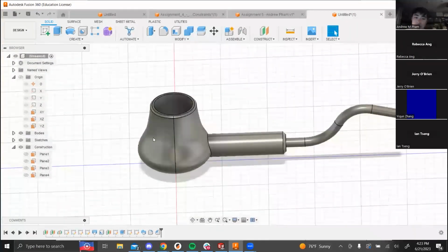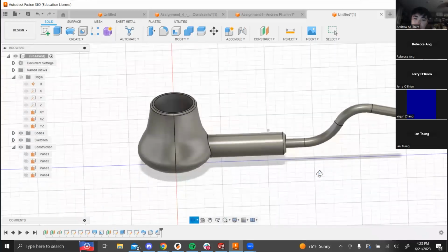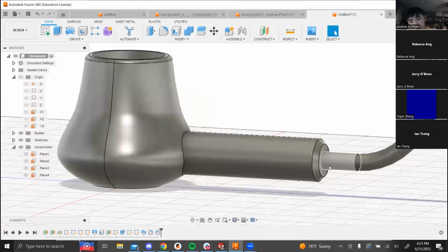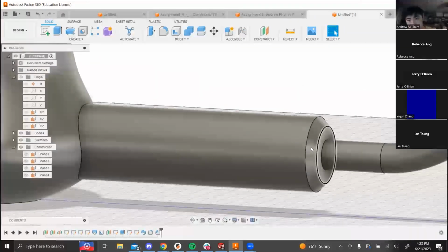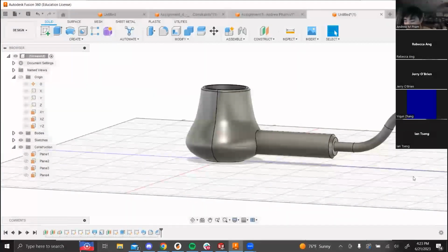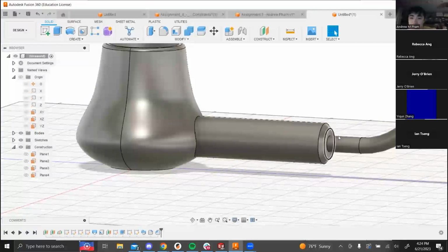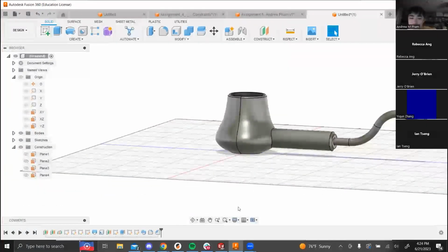You typically want to do these operations at the end of your CAD design, because it makes it a lot easier to edit your other sketches later. So let's say when I was projecting the line for the profile, or I mean the path, not having this chamfer made it a bit more clear, right?